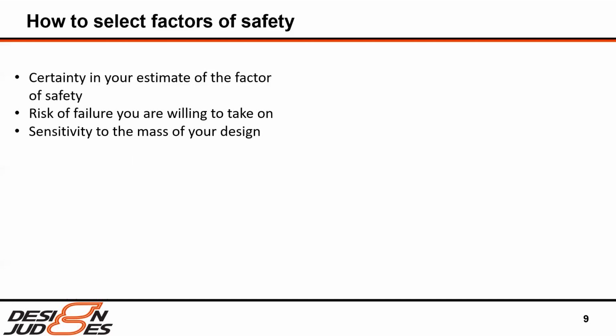Even fatigue analysis should be done for parts with cyclic loading, especially non-ferrous materials, which don't have endurance limits. Ferrous materials typically have endurance limits near half of their ultimate strength, although these general rules should always be double checked, but that's a pretty common one that is seen.